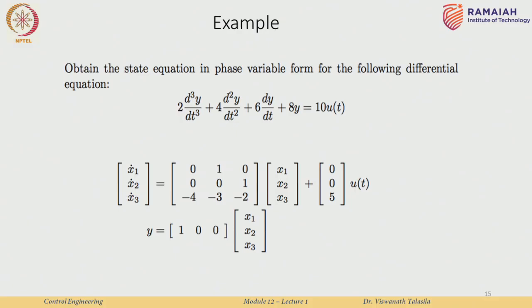We have already done the second order state space model for a mass spring damper. We have seen the nth order derivation to derive an nth order state space system. Let us look at this simple third order differential equation and see how to derive the state space model. What we are going to do is what we have just done for the previous case. Since it is a third order differential equation, we are going to define 3 new variables, x1, x2 and x3.